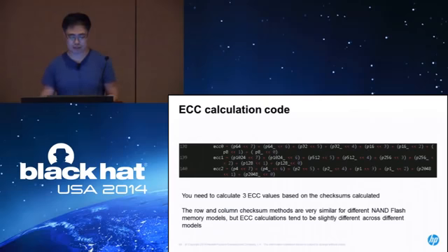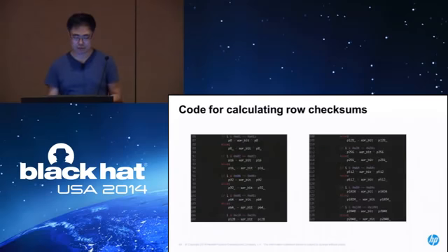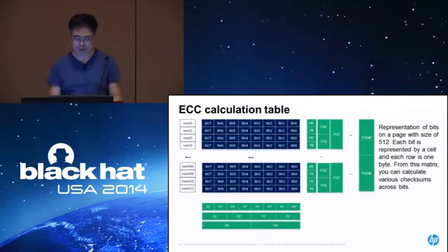And using these 3 bytes, for example, go back to here. If bit 0 is wrong, it will trigger P8', P16', and P32', and so on. It will make all these row parity bits wrong. And on the column side, it will make P1', P2', and P4' wrong.